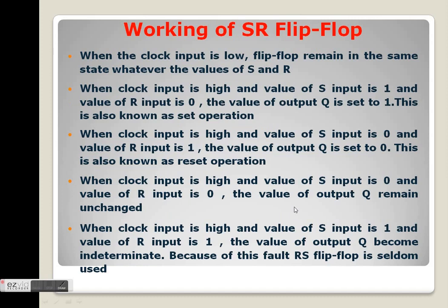Students, let's now understand the working of SR flip-flop. Firstly, we need to understand that when the clock input is low, then the flip-flop will remain in its present state, whatever the values of the inputs S and R. Students, the flip-flop will start its functioning only when the clock input is high. Let's now discuss the possibilities of inputs when the clock input is high.